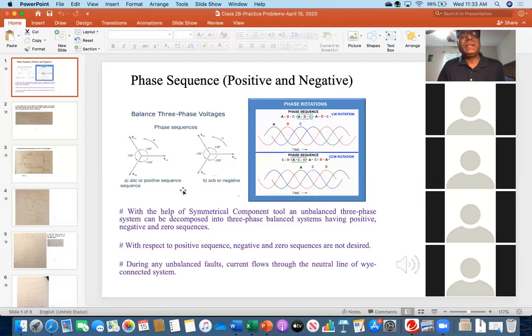Now, why am I discussing this? What is the issue? For example, as I mentioned, the United States has an ABC or positive sequence three-phase system. Now we have a system and you purchased a three-phase device that has ACB sequence. And then you try to connect it with the existing ABC system.